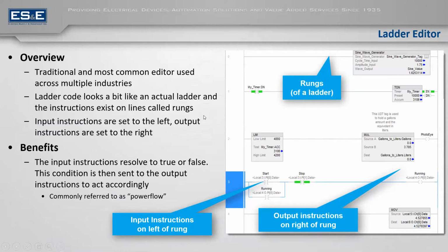It's much easier to comprehend because you have signaling cues that tell you something is happening. Ladder logic is referred to as ladder logic because you have a power band on the left-hand side and on the right-hand side. And if you see green go across, that means that logic is executing. You have continuous flow. Ladder logic stems from electrical diagrams, so that's why you have just contacts and coils, but it has progressed since then.